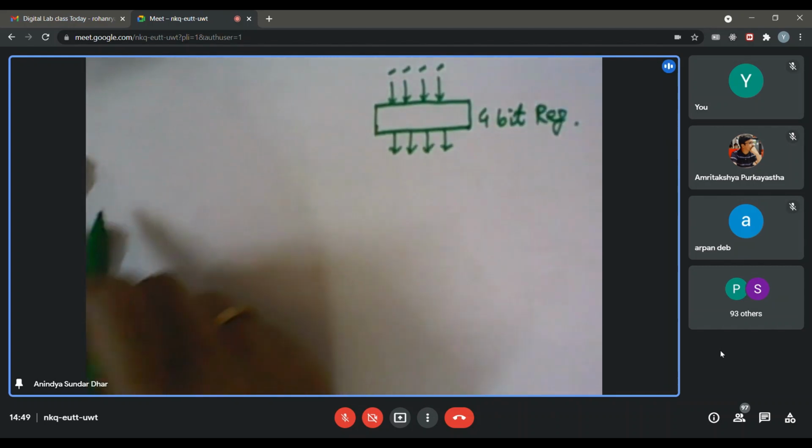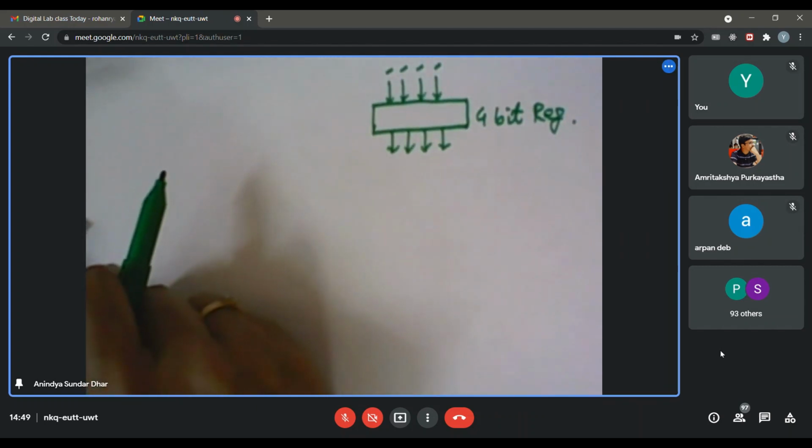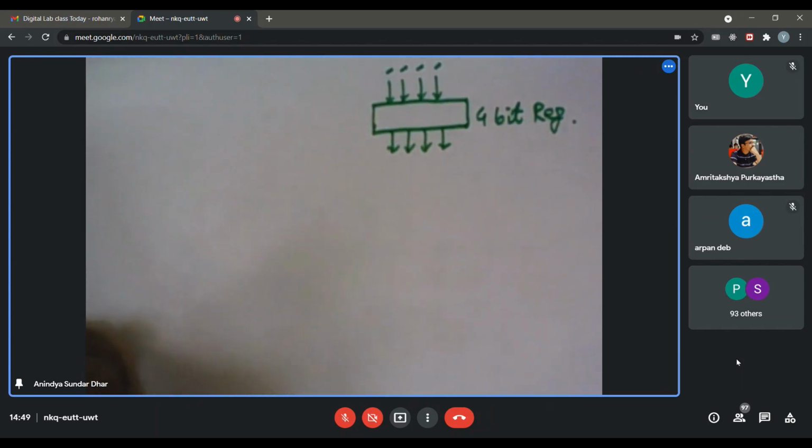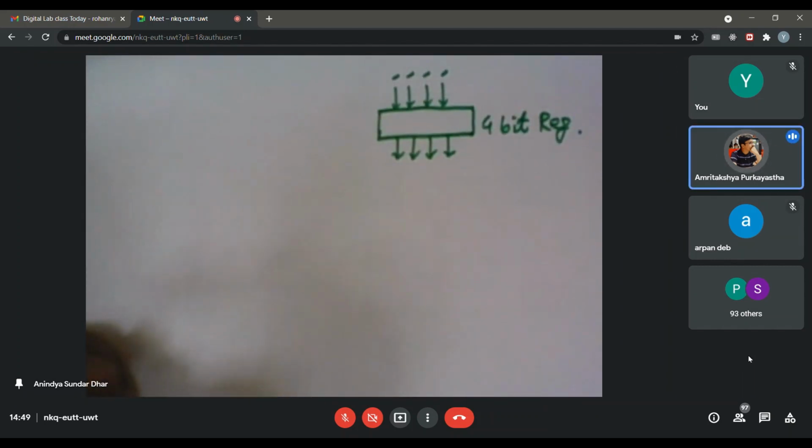So I should have some additional signal for that one, right? So if out of your own interest you have studied somewhere, or you can suggest something from your intuition, how do I do that? How do I indicate that, okay, I want to store this 4-bit number right now, whatever I have presented at the input? Any idea? We use a clock signal to register the number.